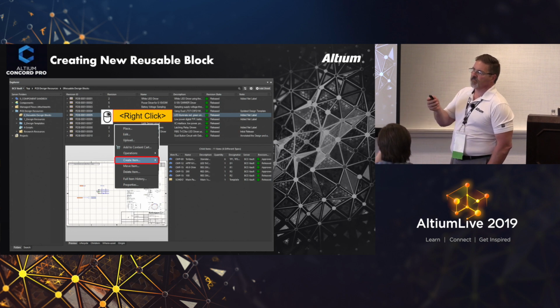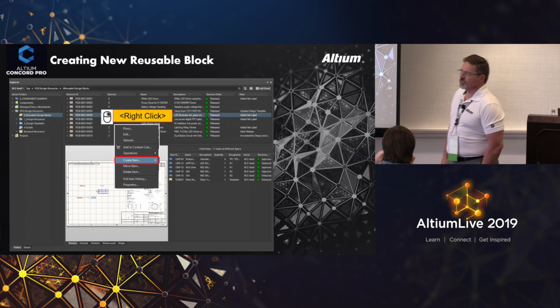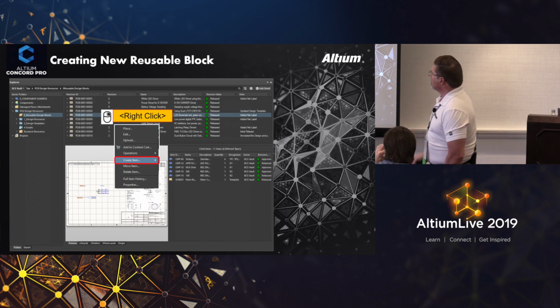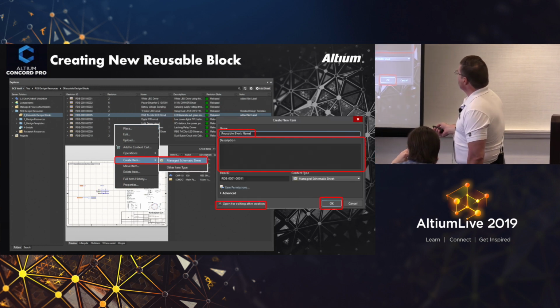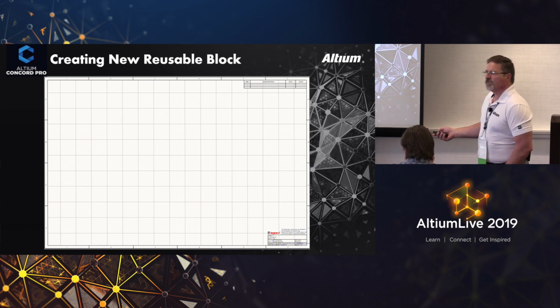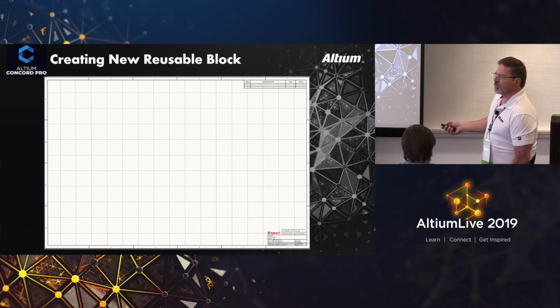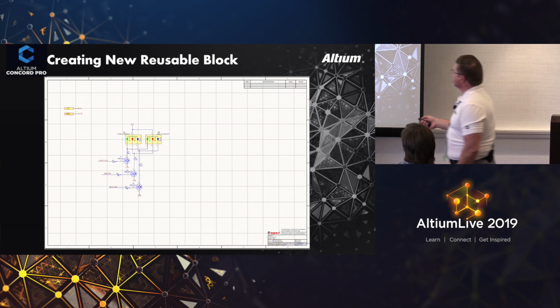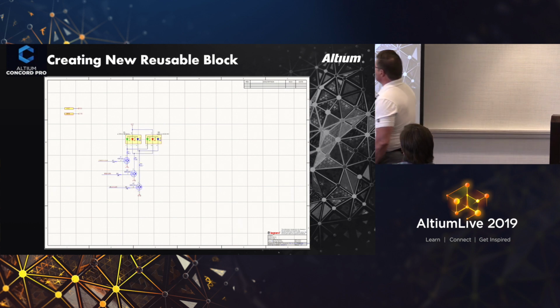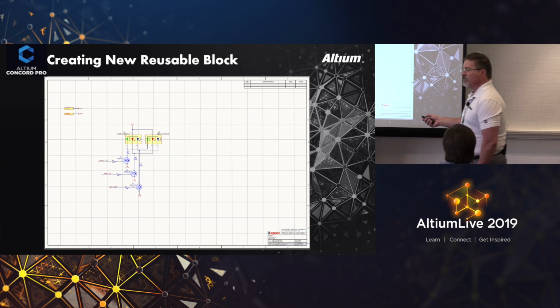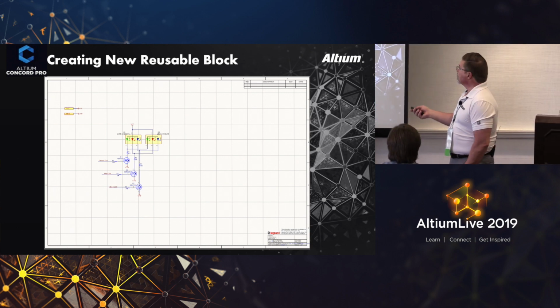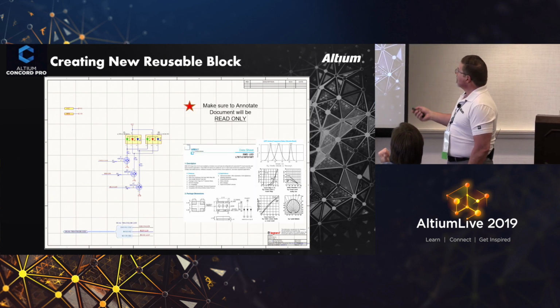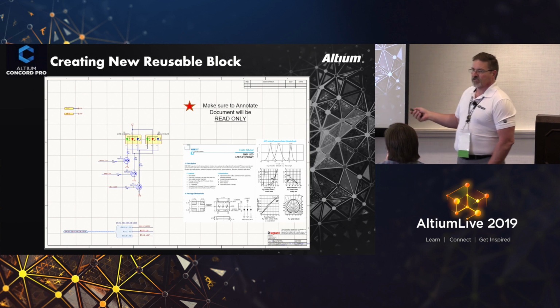Yeah? Now, does that mean the designator follows the component when you go through a sheet? I'm sorry? Do the designators follow the components when you recycle a sheet? The designators themselves are going to be what you set up on your schematic symbol, your default. Now, that's where you bring your annotation in, that you should annotate this.